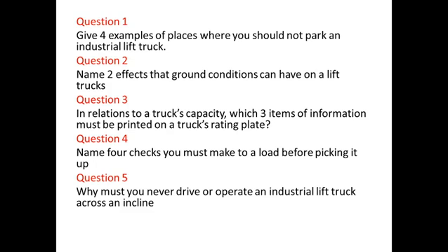You may very well need to widen your forks if the load is particularly wide, for example. You could also check the condition of the pallet. Make sure that the load isn't likely to break through the pallet. It'd be a good idea to also be aware of the nature of the load, i.e. is it a live load or is it a dynamic load? It's going to be moving around. And also the contents of it. Is the content dangerous? Is it a flammable substance you're dealing with, for example?